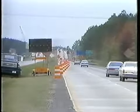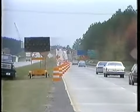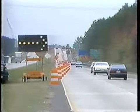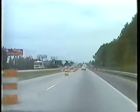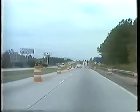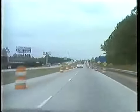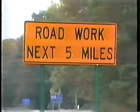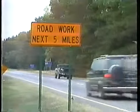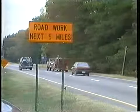Avoid gaps in the traffic control at work zones that may falsely indicate to drivers that they have passed the activity area. For example, if the work includes intermittent activity throughout a 1-mile section, drivers should be reminded periodically that they are still in the work zone. The primary purpose of the guide sign, Roadwork Next Miles, is to inform the driver of the length of the work zone. It should not be erected until work begins.